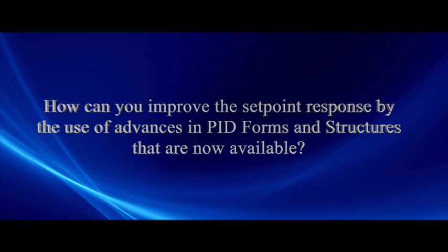And really, that's why in the modifications I say that the rate time should never be more than 1/4 the reset time. I take that view because derivative is overrated, rate time is overrated. And I just want to be careful because I don't know what structure they're using. Even though I tell them you shouldn't do this, just to protect you in all cases, don't ever set the rate time more than 1/4 the reset time.